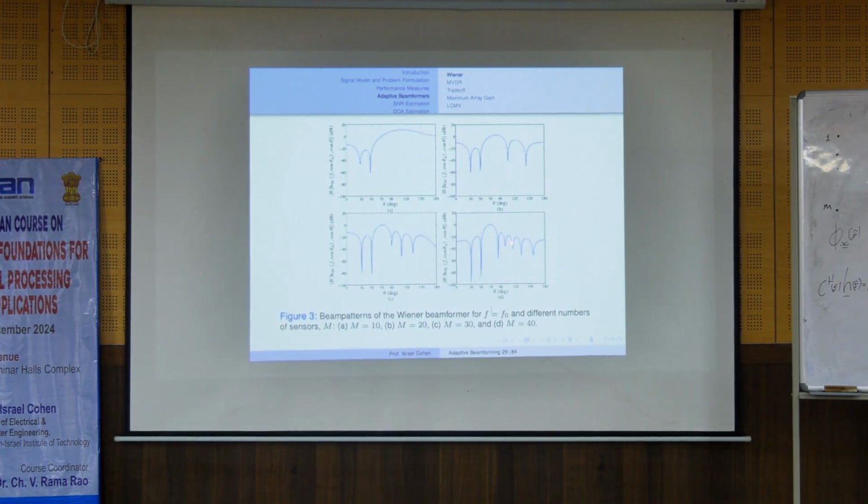So in order to make these nulls lower and also to reduce thermal noise, which is uncorrelated, it tries to lower all the side lobes also. It looks like it tries to lower noise that comes from any direction. So it tries to minimize the width of the main beam because there is no desired source from another direction.